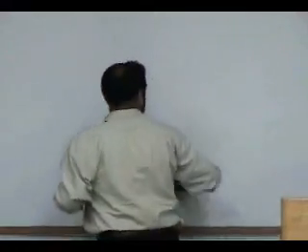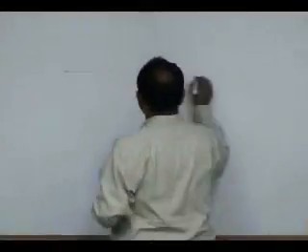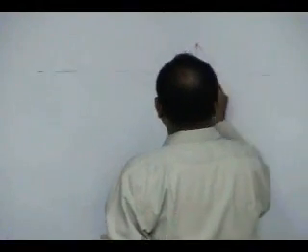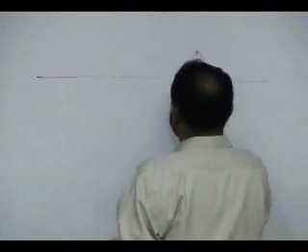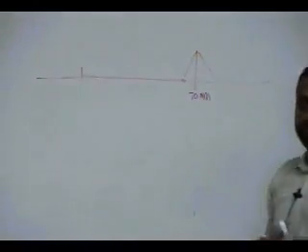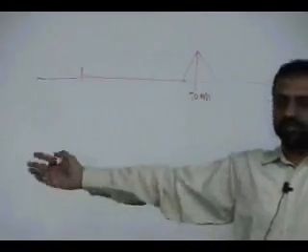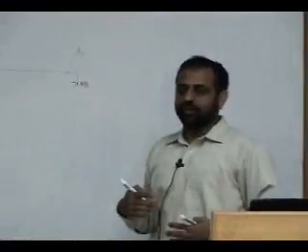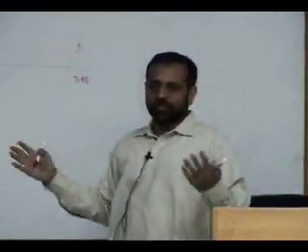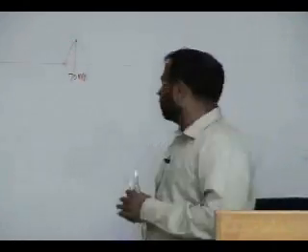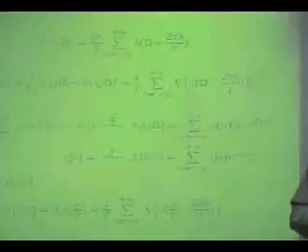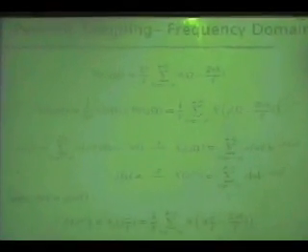But what I really wanted to point out is, though at 970 megahertz you may think the rest of the band is clean, no, it is not. You have to clean the band before you process it in the analog domain, because the band is occupied throughout. So in the analog domain, you keep cleaning the band and bring out your signal of interest. Only you leave that, and throw everything else away.